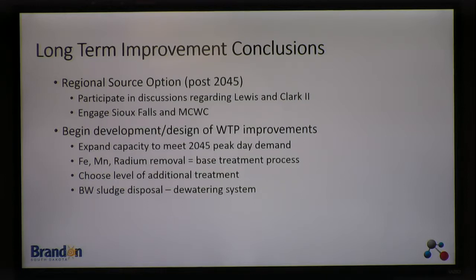That's why I really like the idea of that second level of treatment of the RO process. Here's another potential idea. Design a treatment plant expansion with the option to add RO. It's basically a slab with piping to it and piping from it. You have to incorporate some of the interconnections to make it possible in the future. But basically an RO system sits on a floor. Typically there's a garage door to that area because you're almost always designing with the future in mind. And so an RO skid comes on a truck, you put a forklift on it or whatever, you haul it in, you set it down, connect with the piping and the electrical, and there you have an expanded facility.